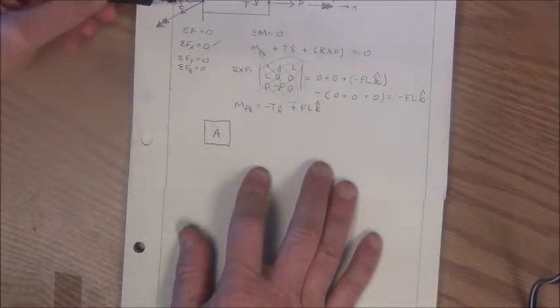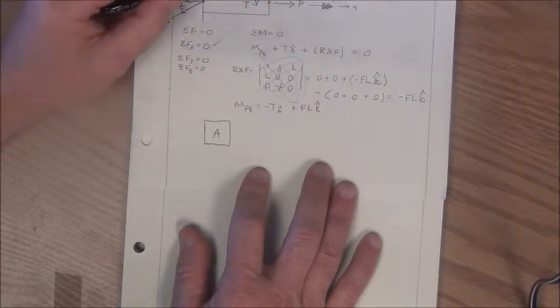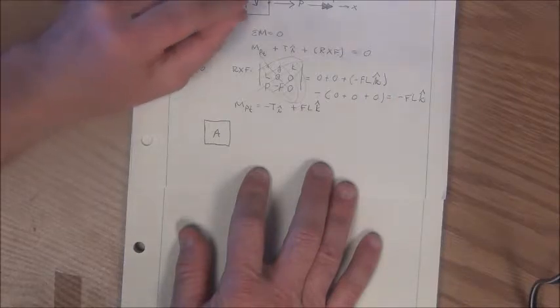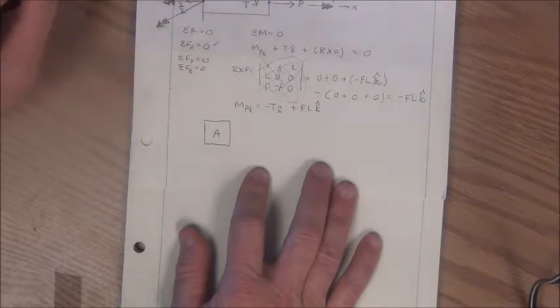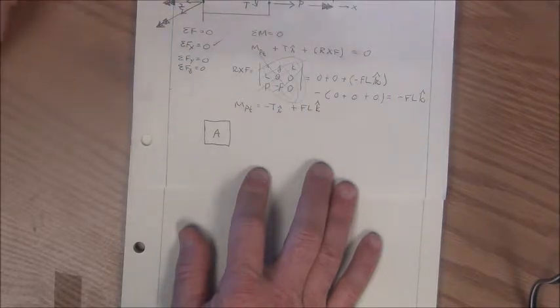So starting off with my P load, or my axial load, it's not a moment, so there's no way it can do MC over I. It's not a torque, so it can't do TC over J. And it's a normal force. It's not a shear force, so it can't be a V. So there's no way that this normal load P, which is perpendicular to the cut plane of interest, can be anything but sigma equals P over A.